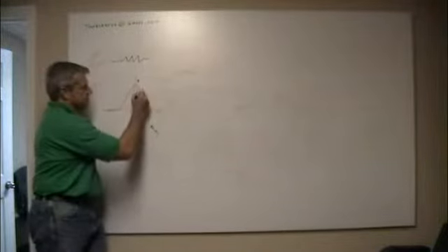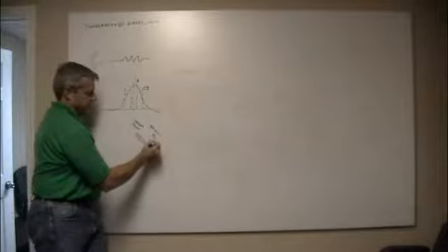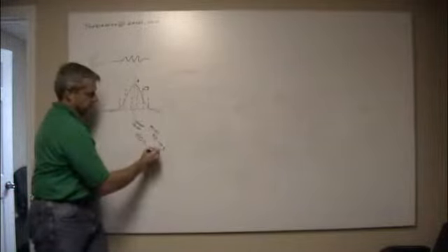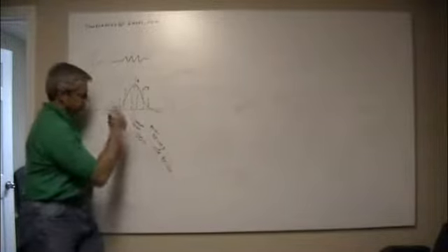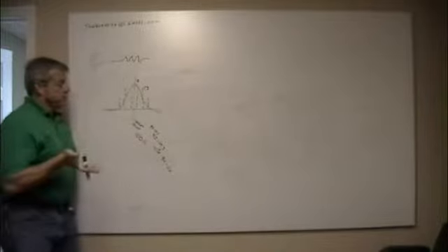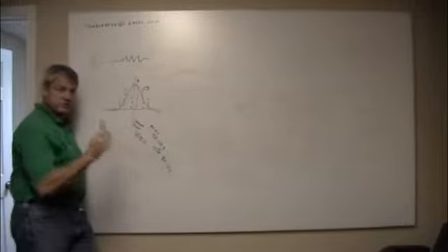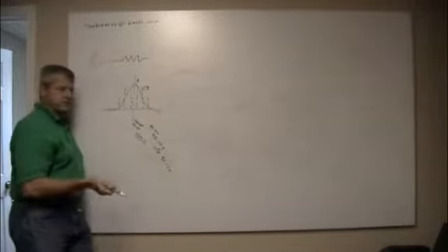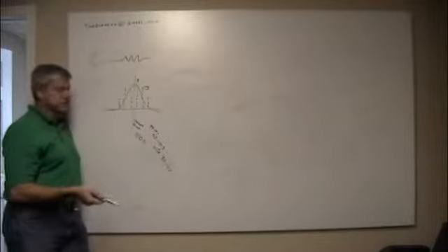And then there's some probability of 5%, so 95 to 105. And then out here, 10%, 90 to 110 ohms. So when you design sensitive circuits, you've got to pay attention to these things, because if you say, oh, I want a 100 ohm resistor, you're never going to get exactly 100 ohms. It's going to be 100 point something or 99 point something.